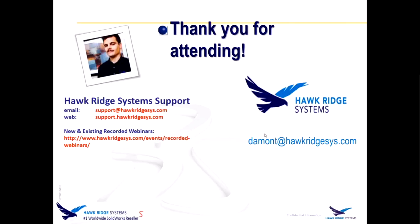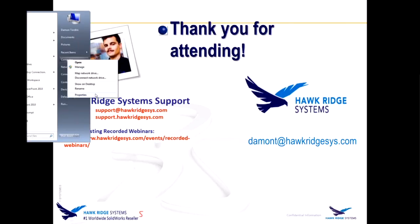Melkor asks, is there a limitation in the number of nodes or number of parts that you can bring into a fatigue simulation? Good question. Actually, there isn't a limitation built into the software on fatigue or any other kind of stress analysis. The limitation is going to be on the hardware that you have in your computer and how fine you're trying to make the mesh. So as an example, on my computer, which is an HP laptop, if you want to take a look at my system properties here, I have about 8 gigs of RAM.